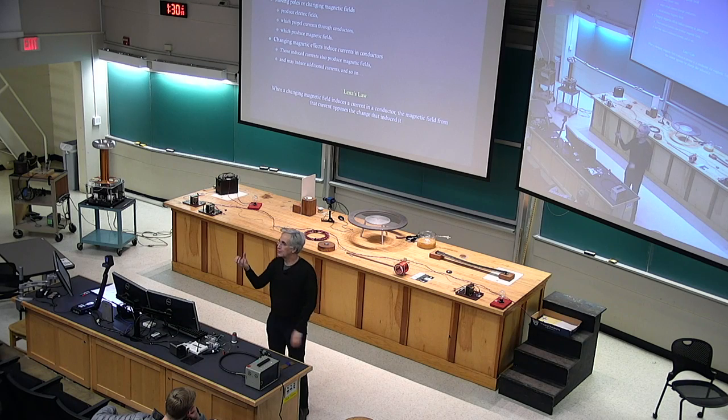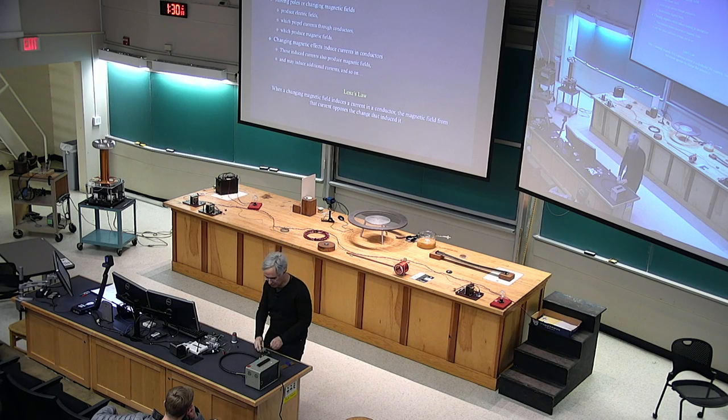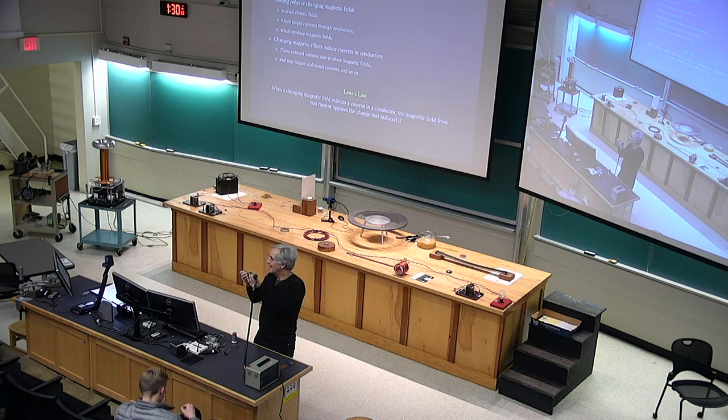The overshoot in the doorbell, during the overshoot, bing, it hits the first bell. Ding. And then it goes back in the middle and it's sitting there until you release the doorbell and stop the current. When that happens, the spring returns the piece of iron which has been hovering here. The spring pulls it back to this position. But in doing so, it overshoots again and hits the other bell. That's the dong. So when you hit the button, ding, dong. Is that okay?